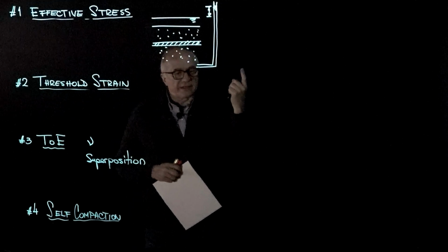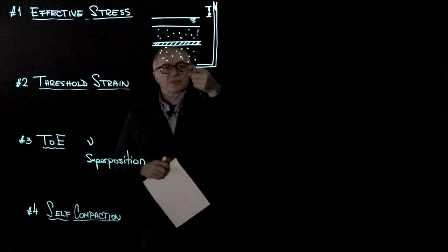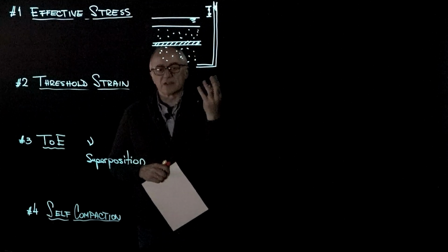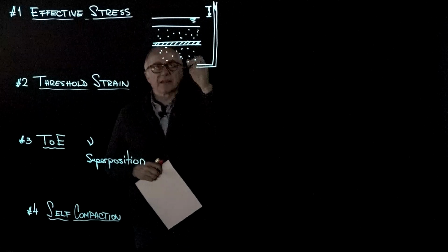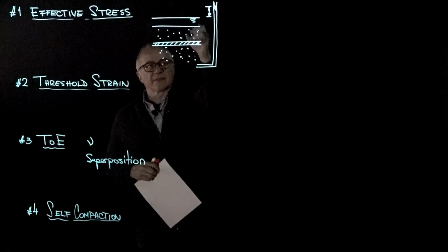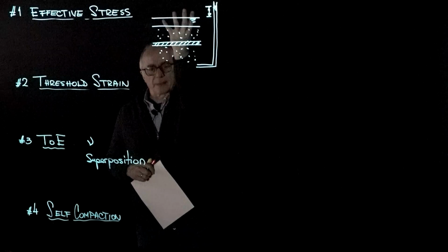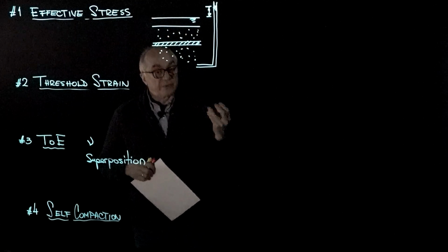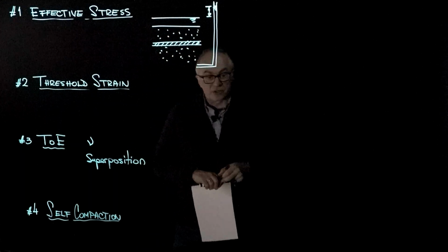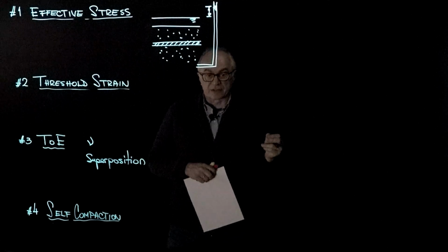And there is a unique situation that there is high pressure from underneath. This is an artesian case, which can be quite dangerous because if you begin to excavate, you may have a bottom blow up. So we need to understand the situation with pore pressure and effective stress.